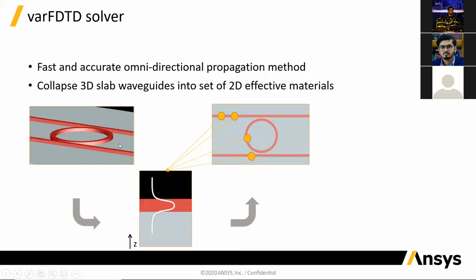So imagine this ring modulator where you have oxide cladding or oxide substrate everywhere, and then you have this silicon layer with a particular thickness, and the thickness is uniform. What you do is you look at the slab of the silicon and you calculate the slab mode in that silicon layer, and then the effective index of the slab mode becomes the index of the material as you convert this structure into a 2D structure. Everywhere you have silicon, you simply use the index of the slab mode as the index of the silicon material. That way you can run a 2D simulation, but by using the index of the slab mode instead of the index of the silicon layer, you also take into account the multi-stacked layers that you have in your simulation. And so that allows you to get accurate results even though you're doing a 2D simulation of a 3D geometry.